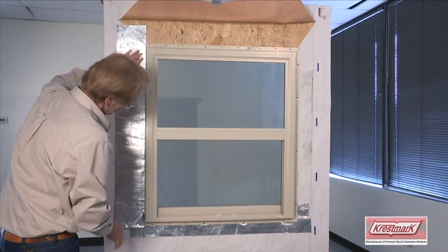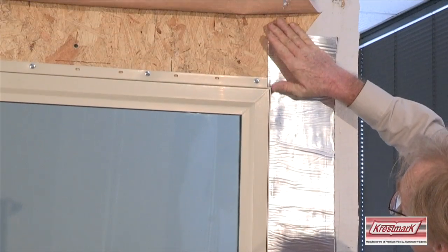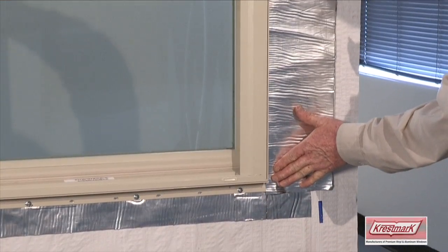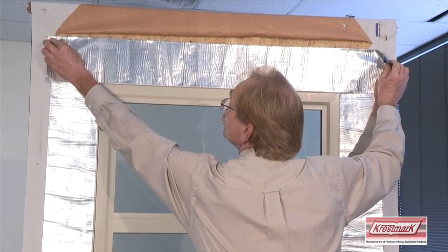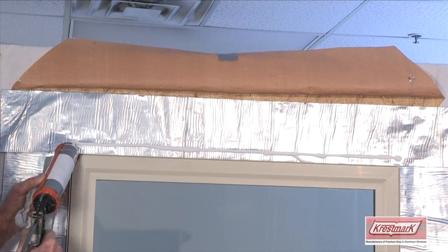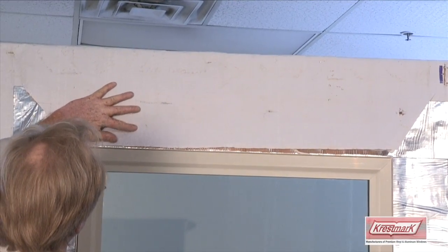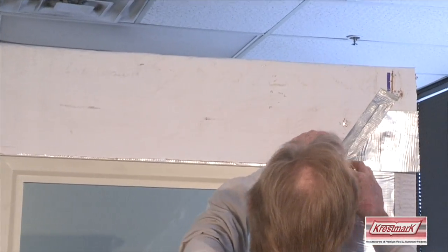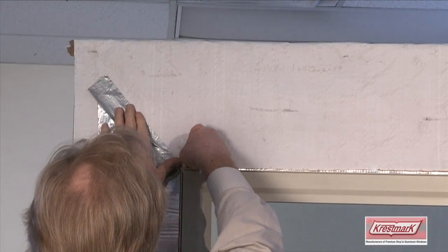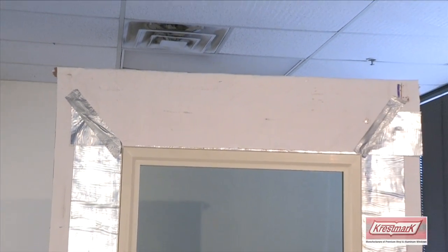As seen before, the sill flashing was installed prior to the window. The side jamb flashing starts 5 inches above the window, down the nail fin, and extends past the sill flashing. The head flashing overlaps the jamb flashing as seen here. Once the flashing tape is installed, run a bead of caulk along the head flashing tape to adhere the previously cut vapor barrier. Duct tape the remaining cuts in the vapor barrier. The methods seen here are best practice and will help ensure a weather and watertight barrier for the end user.